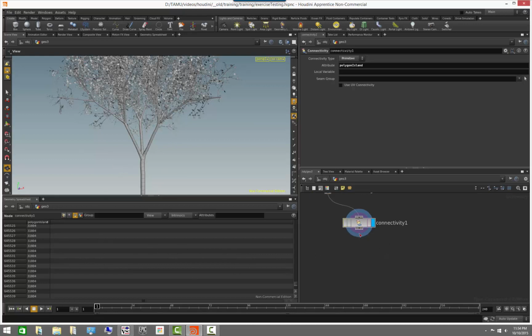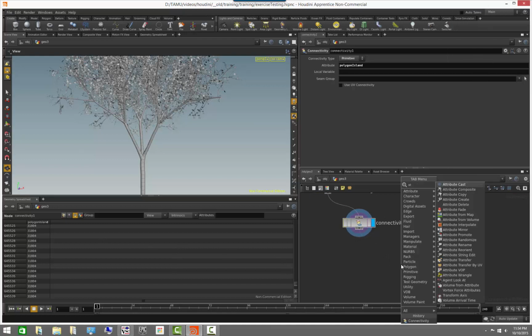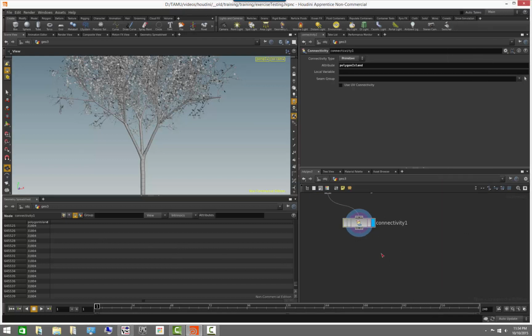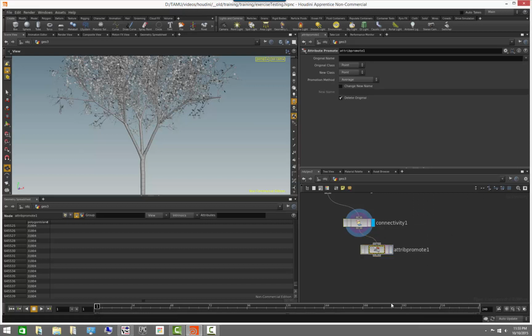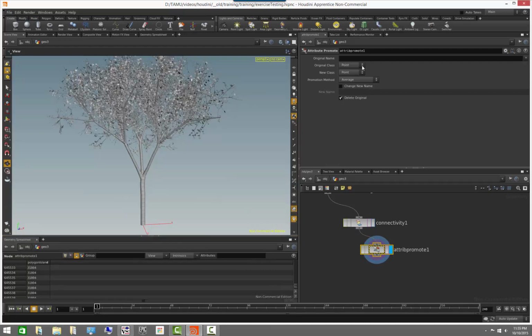For that, all that we have to do is to create an attribute promote, okay, as in promotion. And I'm going to come here and say that my original class is primitive. I'm going to explain a little bit in a second what this does, but I'm going to switch my class to primitive, my new class to detail.